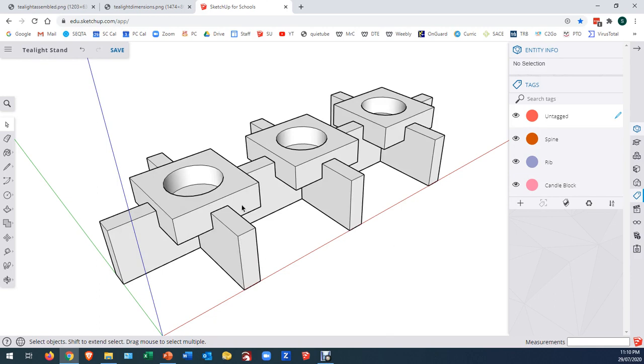And so what is useful in almost every case is that whenever you're creating tags, it's always a good idea to create an additional tag, and I generally call that assembly. If you've got a more complicated item that you're modeling, you may have some sub-assemblies which may have specific names. For instance, a cabinet may have the actual cabinet case, the door and the drawer. They would be sub-assemblies, but you'd have an assembly of the entire cabinet that you want to see.